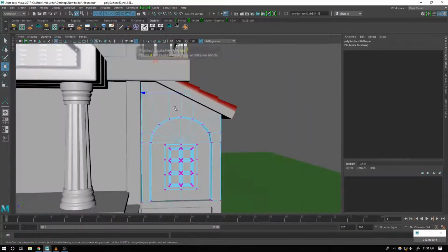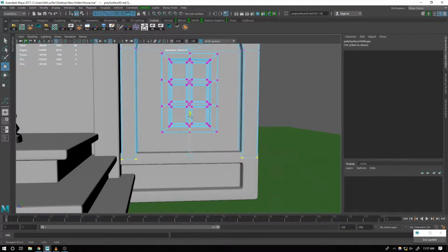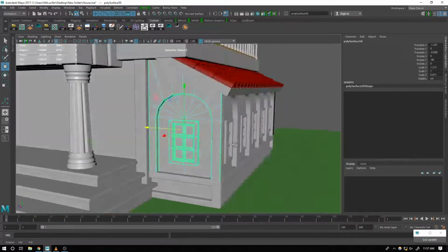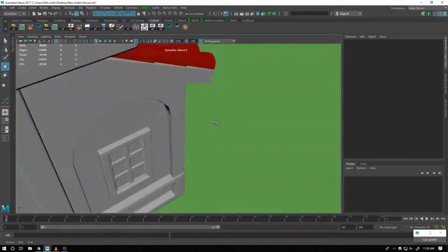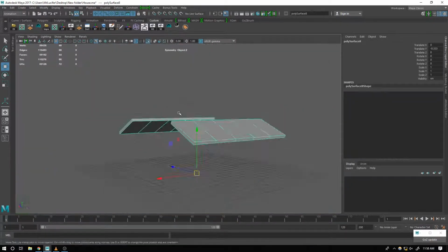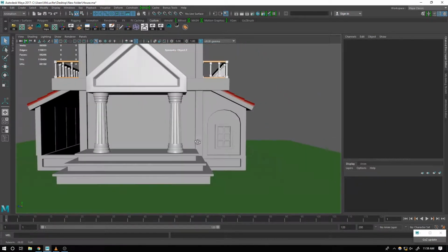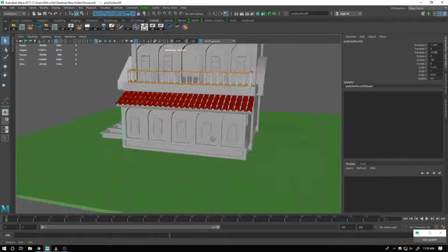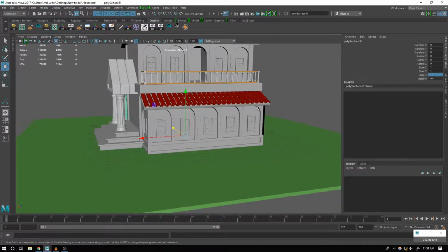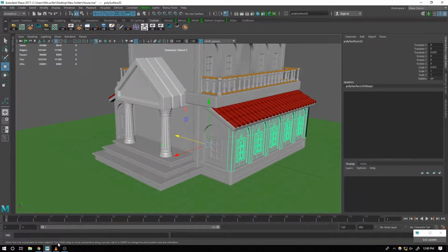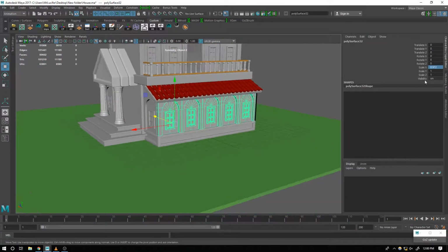Yeah, so as you see, I straightened the loops along with the tiles. Yeah, it looks cool. Now I'm going to add some bevel. Always make sure you add some bevel to it, because otherwise your whole model is going to be blade-like sharp, and that really doesn't help when you want to create something good. Everything has a smooth curve on its edge, rather than a blade or paper, anything like that.